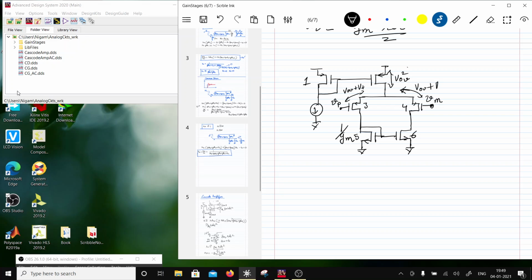Then you have an AC on top of it. Now for transistor 3, if you put in a VP signal, let's say this is a fixed DC voltage, so you can assume this to be a small signal ground. The voltage here would still be VP, because transistor 3 is a source follower.